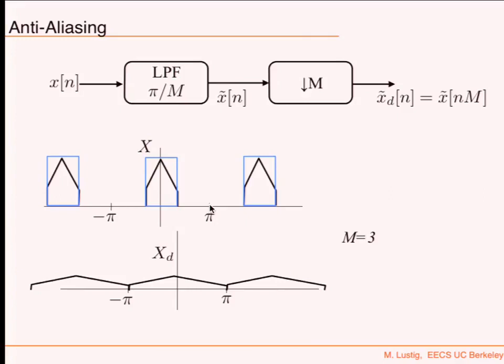Before you downsample, you're going to have noise. It's going to be an FM signal, so you're going to have the stereo and the pilot and all the other stuff in the high frequencies. That's not good. You're going to filter, and then you're going to downsample. And you're going to see how beautifully this all looks.